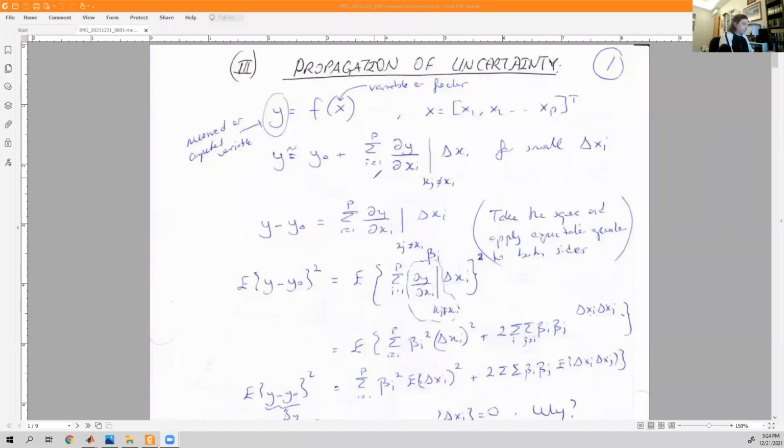So, what is propagation of uncertainty? In a nutshell, the idea is very simple. Up to this point, I have given you some simple examples of how to deal with uncertainty. For instance, we measured only mass, we measured only volume, things like that. What if we would like to compute or measure the Reynolds number? You have to measure each of the variables in the Reynolds number, like density, viscosity, average velocity, and what else do we have? Diameter. And then we are going to divide and multiply all of them according to the equation of the Reynolds number.